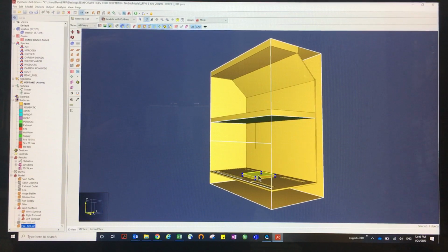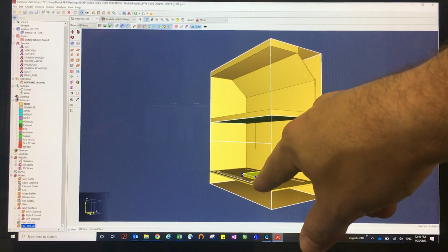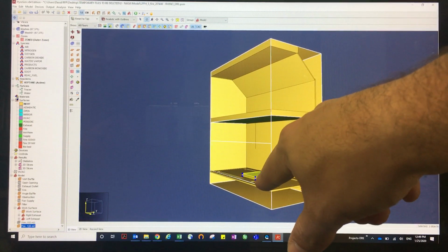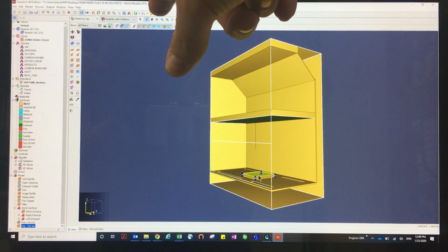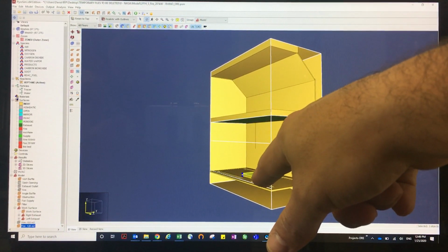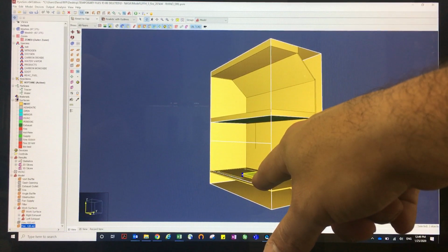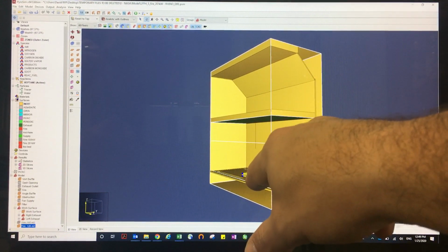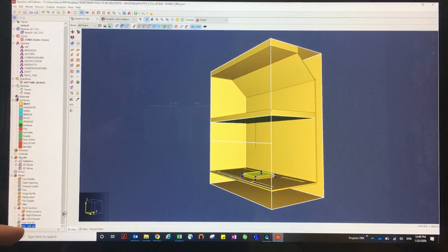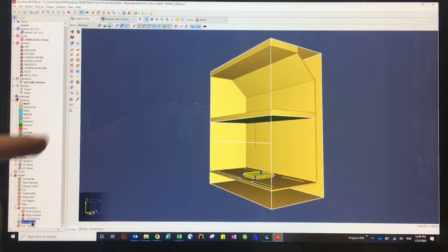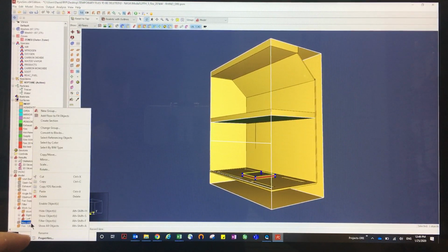So on each different scenario, this one represents the area for a fire that is 201 kilowatts. For the scenario where you have only a 55 kilowatt fire, this should be smaller, right? Because the area is smaller. So in that case, I don't show it here, but in the other model you will see that this box is already created. So let's say that is this one.